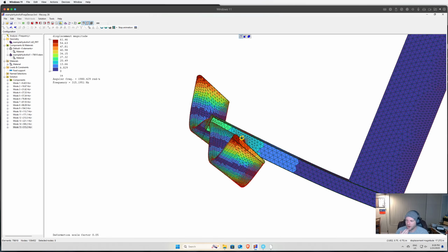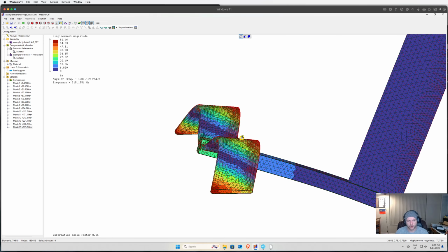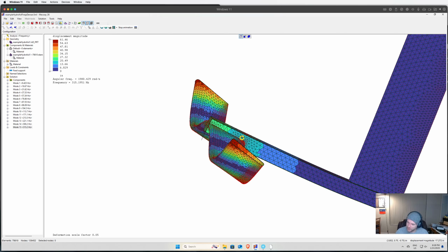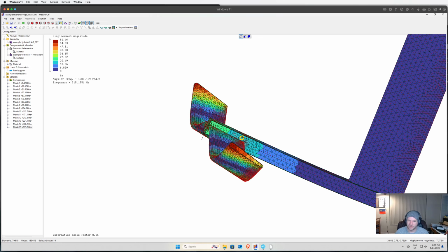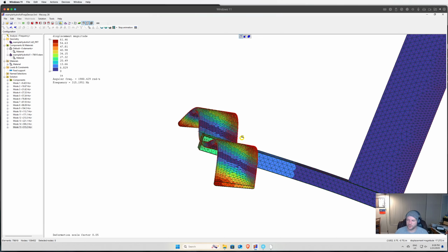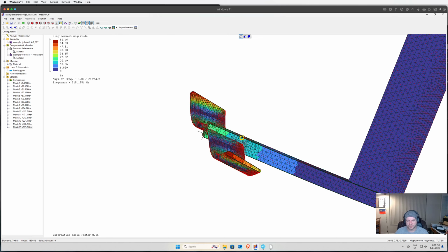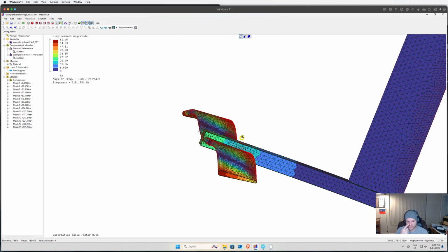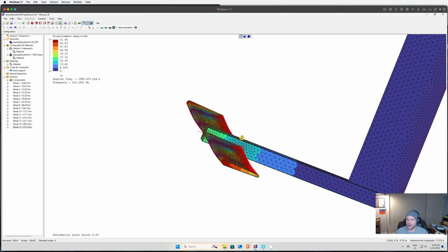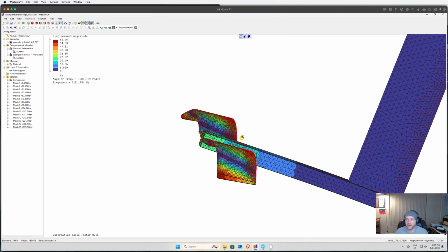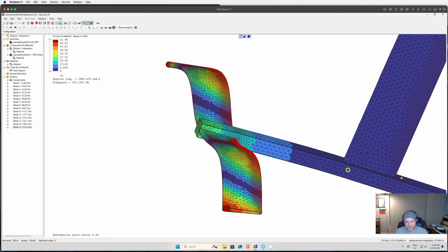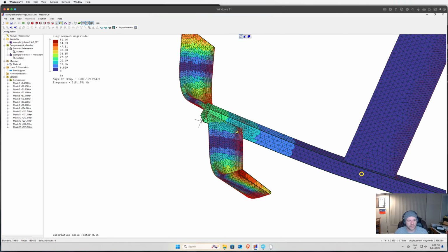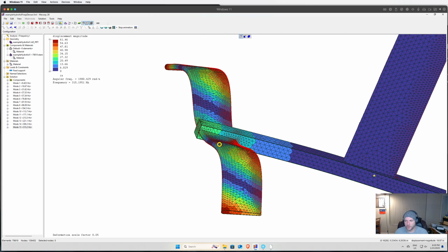I think that also you could look at the stresses. I'm not too bogged down in the stresses with this, because in this case, I'll probably check it at some point, but I really do think that the stiffness of the fuselage, the wing, and the mast completely dominate the equation. I think that if you make these stiff enough, they're probably strong enough to survive. Now, where that is not the case is where you have these connections from like the mast to the fuselage, from the fuselage to the front wing and rear wing.